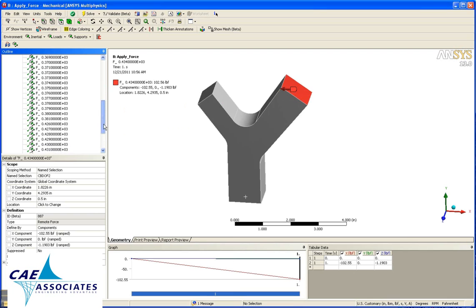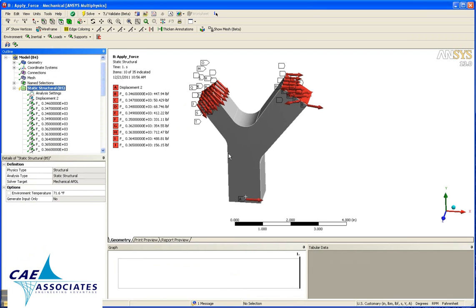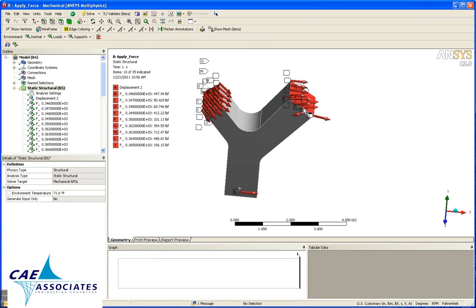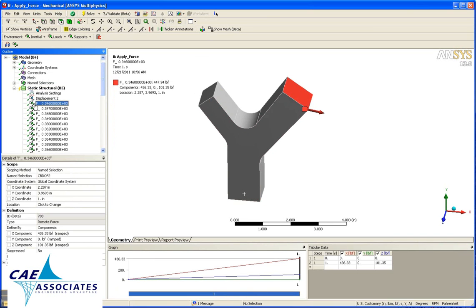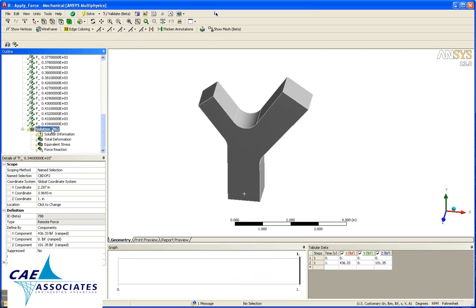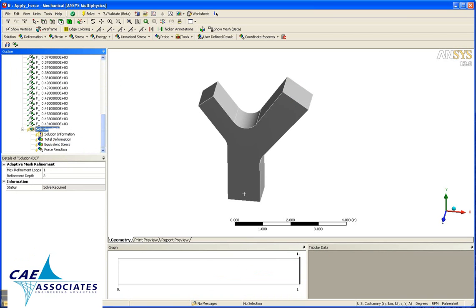So this finished. Now we can take a look here and see all the different remote forces that were applied to the model, corresponding to the cut boundary loads from maybe the global model applied to this local submodel. Each of the remote forces is tagged with the name under which the data came from the file. So this is the node number, and you can look at the XYZ positions, force XYZ, and just verify the data if you want. At this point then we can go and solve the model.